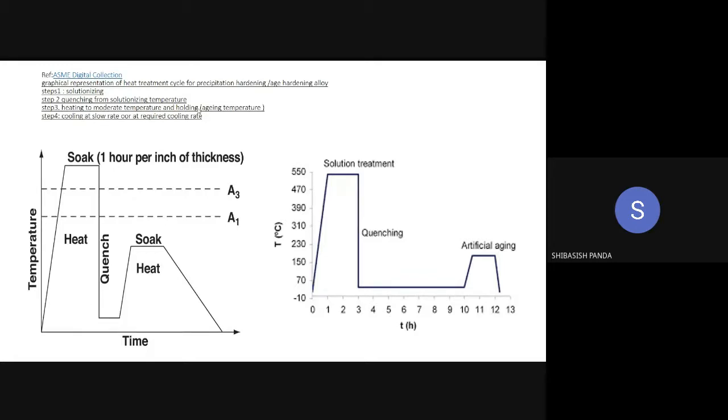And the important point is, sometimes cementite particles get easily soluble above about 650 degrees centigrade. They start dissolving into the austenite matrix. But what about niobium carbide and vanadium carbide? They do not dissolve easily. They need a high temperature, around 1050 degrees centigrade, above 1050 or above 1100 degrees centigrade.